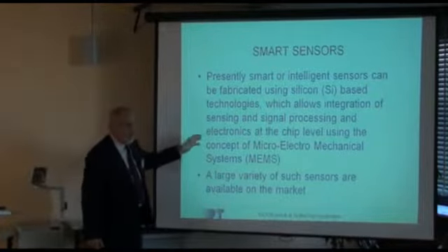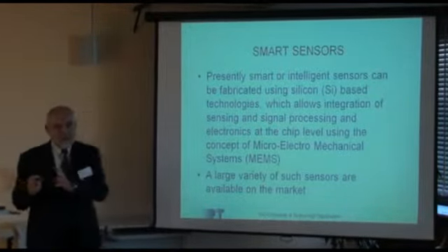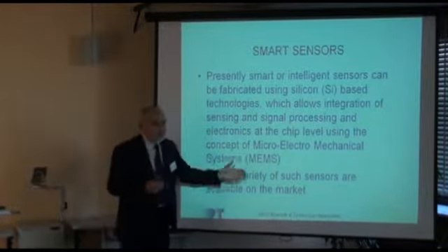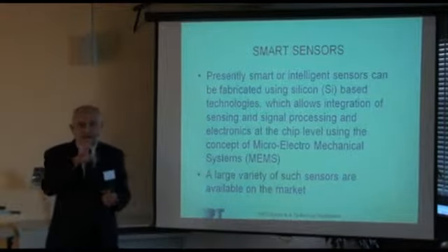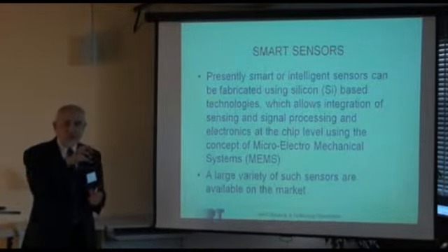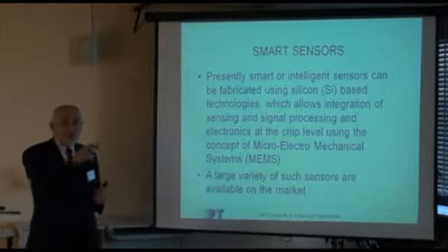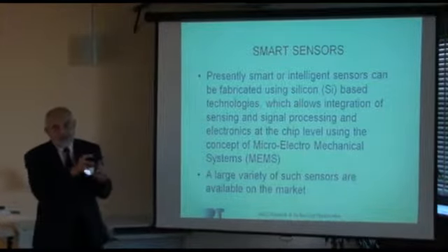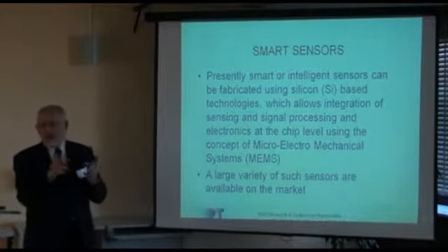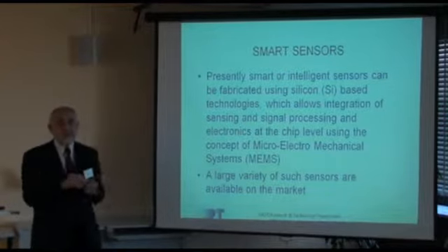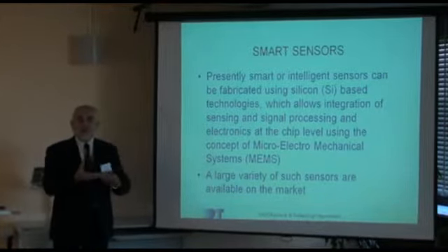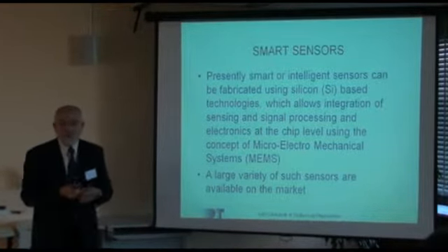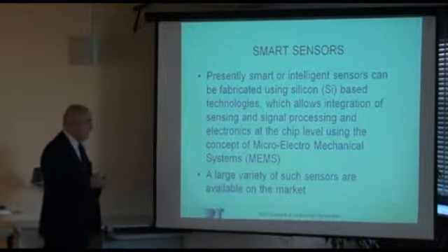Now, if one would double that capability with microelectromechanical system sensors, what does that mean? A microelectromechanical system is a device that contains a mechanical component, a sensor, and electronics that process what the sensor measures, and the big advantage is that this block is next to the sensor. No noise, no stray noise, nothing. And then eventually it transforms the signal from analog to digital and sends only the digital signal out. That would be the idealistic approach for a sensor.